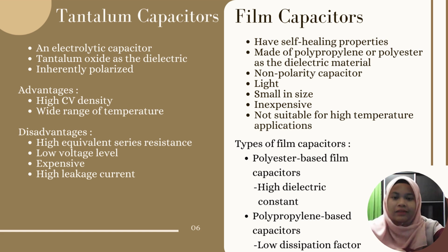Next is the tantalum capacitor. Tantalum capacitor is an electrolytic capacitor, and the tantalum oxide acts as the dielectric of the capacitor, and these capacitors are inherently polarized. Tantalum capacitors have a highly porous anode, and this means that it can provide a large dielectric surface area. Due to this, it has extremely high CV density with a wide range of temperature.